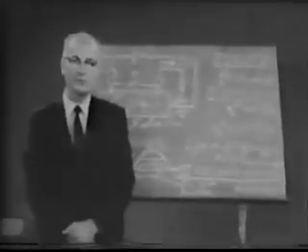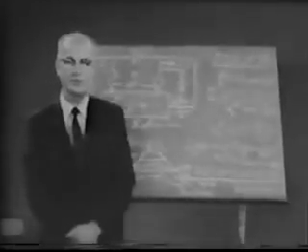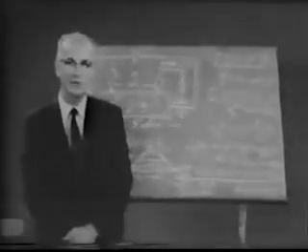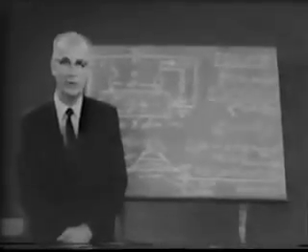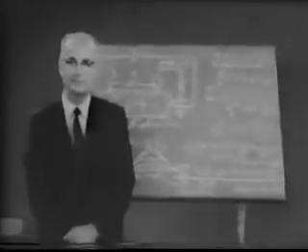Similar experiments can be carried out with p-type germanium. The results give values for mobility, diffusion constant, and lifetime for minority electrons. You have seen the hole pulse in n-type germanium move in the direction of the electric field. Had we used p-type germanium, we would have found the electron pulse to move in the opposite direction.